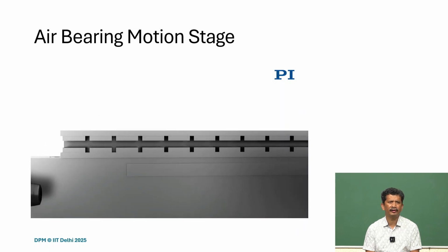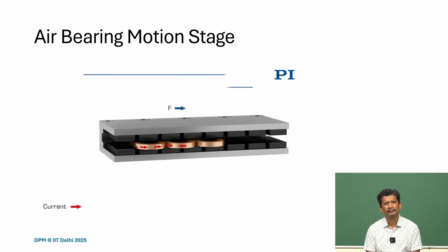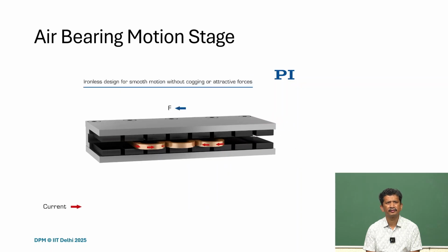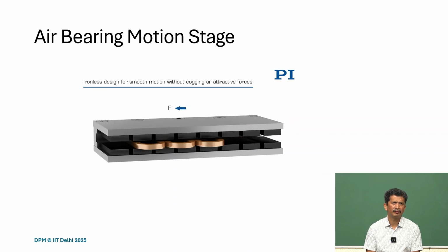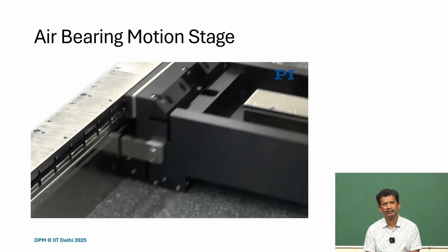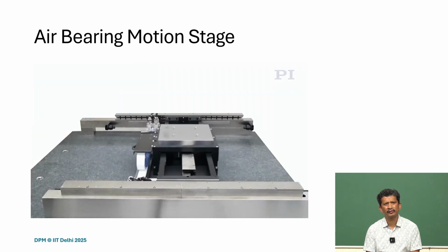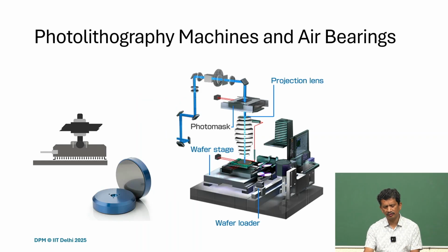There are direct drive linear motors there. So, they are directly embedded on the linear guides. Once energized, the magnet will be stationary and the coil, usually lighter, will be with the motion stage, and it can move freely. So, it's a direct drive, so there is no error associated with the transmission. And of course, there will be sensors there. If we look at these designs, the key component we have is the air bearing.